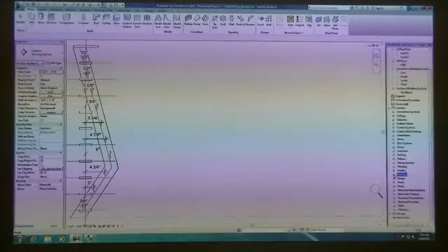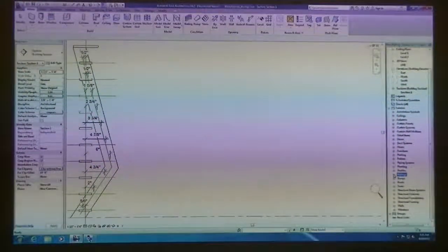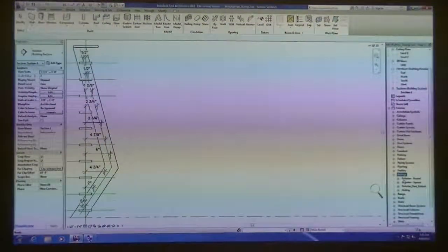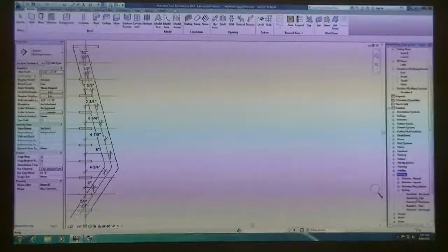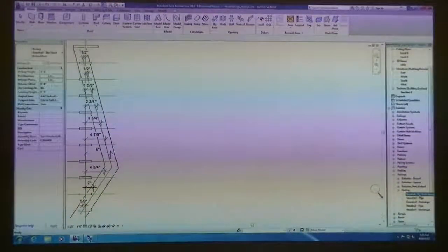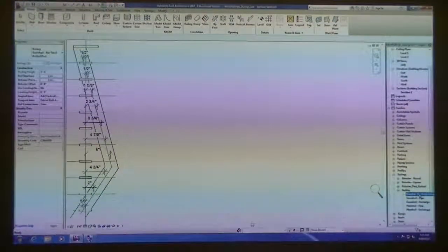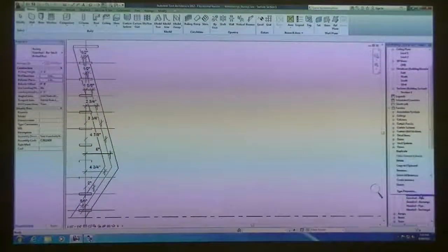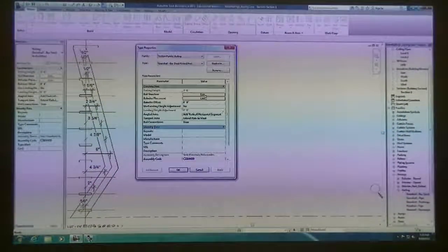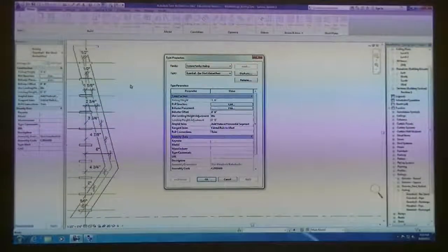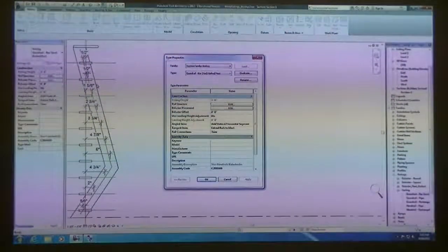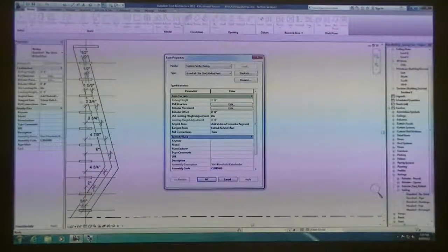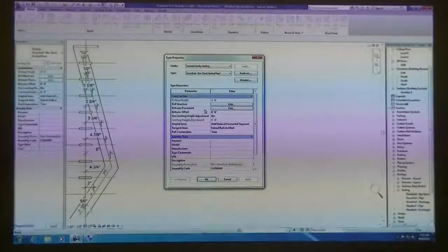Railing systems. Where are you at? There we go. Under railings and then railing, I can now pick my guardrail box stocked or bar stock kinked, right click on it, and then choose the type properties. I went that method so that when I selected my railing system, all of my selections still remained blue, and it was hard to read the dimensions and all that.